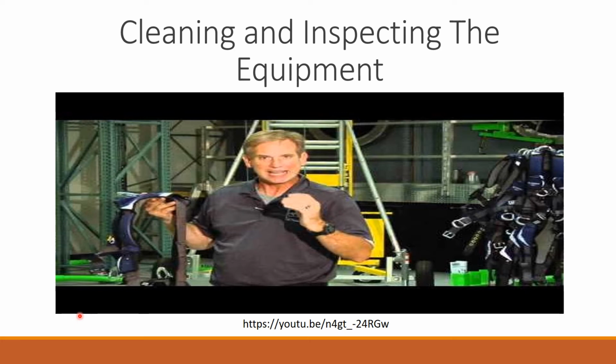For your retractable lifelines, the way you inspect those is you make sure they lock, that they do what they're made to do. You pull out the lifeline at a fast rate, and you make sure that it locks and is able to hold weight. The other equipment is typical, your winches. Just make sure that the cable is all good and the winches actually work. Just make sure everything is in working order.